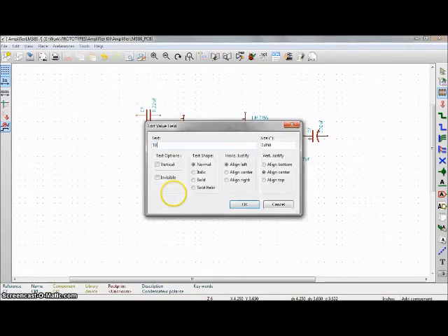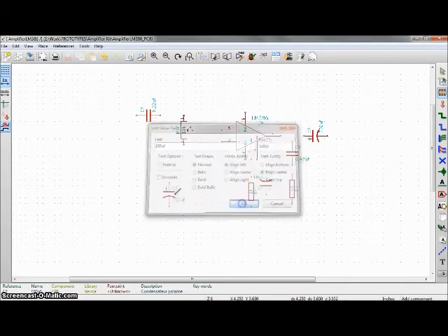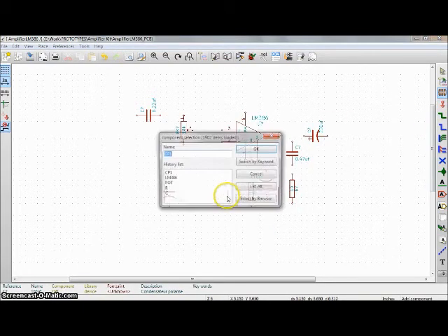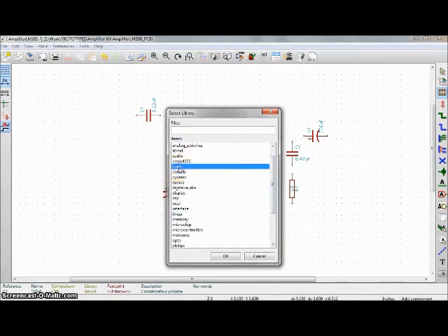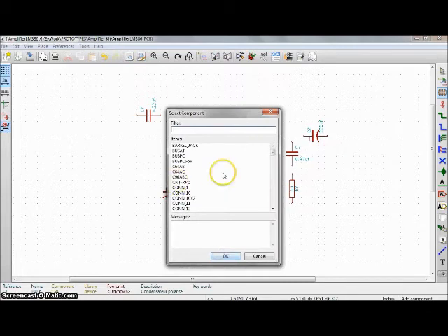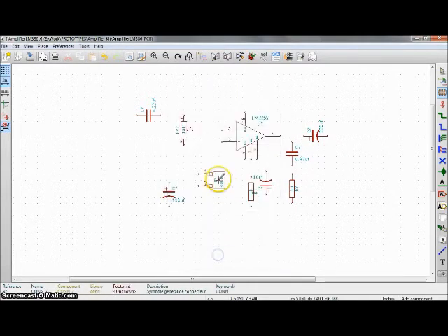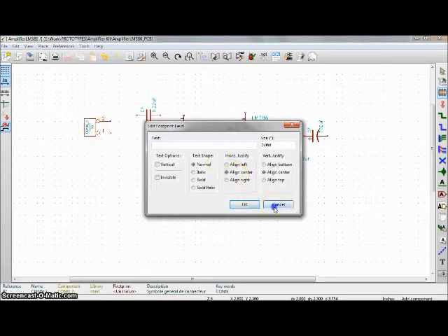I also want some input and output stuff, so I use the connectors library, and I put down 3 two-way connectors. So it's con_2 that has connectors in, rotate them around. There's one. Plonk that down. Plonk another one down.